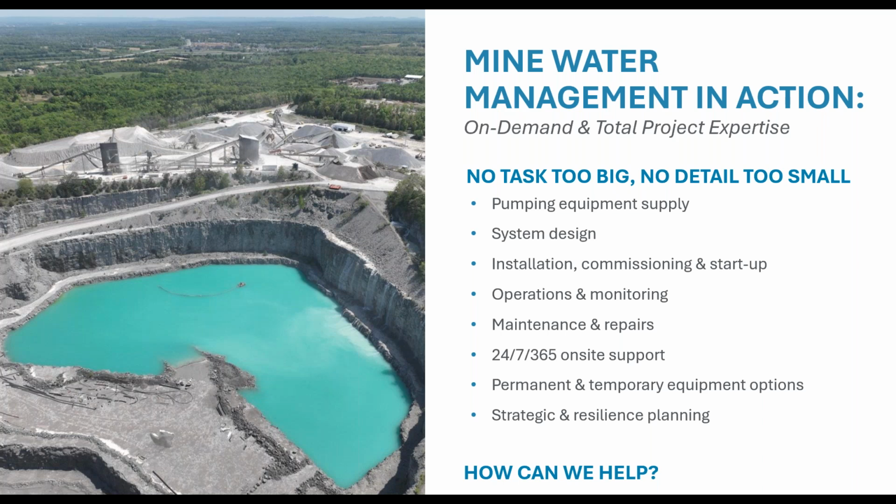I think that, if upgrading the materials of the seal were not sufficient to manage the material being pumped, then the next step would obviously be to evaluate how to reduce the amount of sediment that is needing to be pumped. And that could be, like we mentioned, suspending the pump, either hanging it from a ceiling if it's underground, or using a floating barge system, but basically trying to keep the pump above the heavy sedimentation at the bottom of a sump.